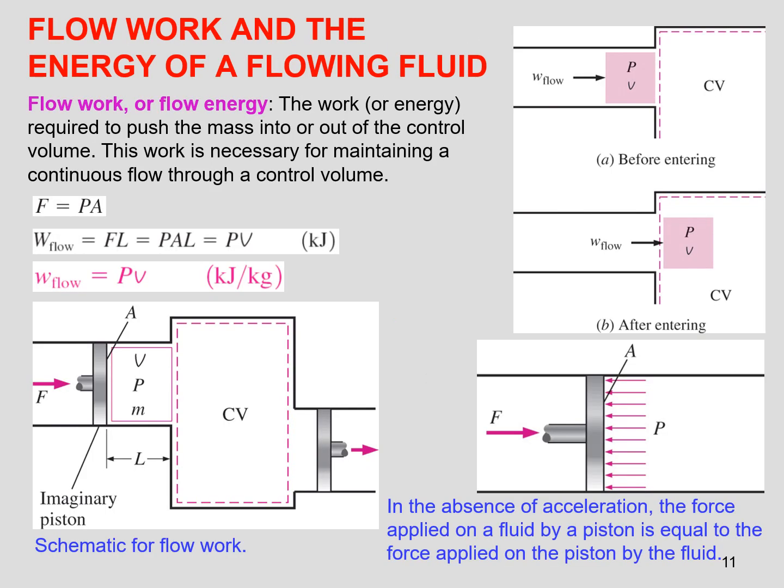So let's talk about flow work and the energy of a flowing fluid. As we know from our studies of physics, we classify energy as either kinetic energy or potential energy. Well, there's another sort of energy involved that we find very useful, which is known as flow energy or flow work. So back from physics, we know that force equals pressure times area, and work is defined to be force moved through a distance, F times L.